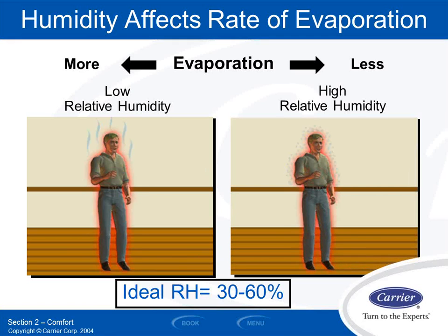If it's the heating season and my body's trying to save some of the heat and I don't want to give it up as quickly, I prefer to be in a more humid environment so I don't give the moisture up as quickly. I don't give the moisture-based heat up as quickly. That's why I typically in spaces will add a humidifier and use that in the wintertime, and will dehumidify in the summertime.